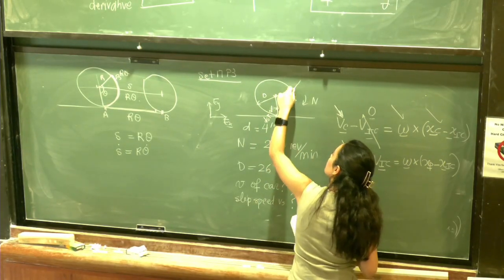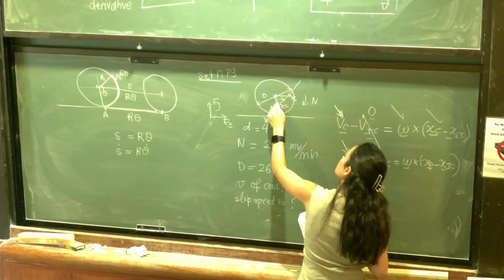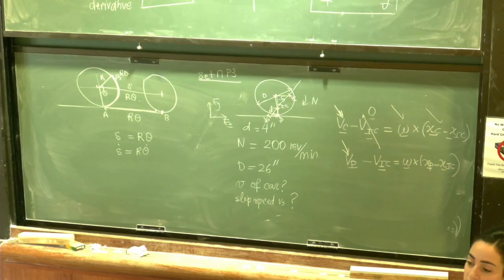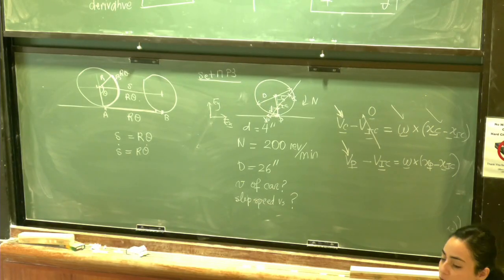So I can draw the velocity profile like this. Make sense? Yes. Would the omegas both be the same because they are both on the same wheel? Yes, exactly. So P, the IC, and the center of mass, they all behave as material points on the same rigid body.